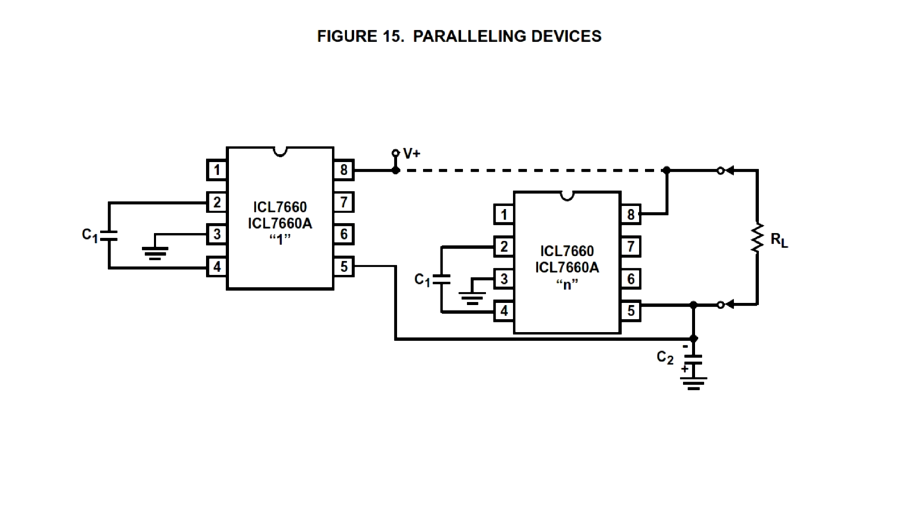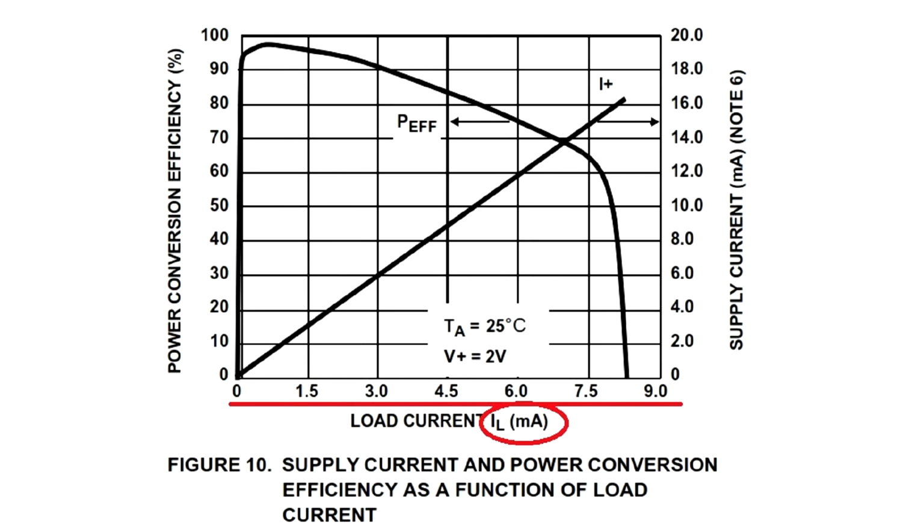But talking about the allowed range of currents, the biggest drawback of the charge pump becomes obvious. A single charge pump based on the ICL 7660 can only deliver a couple of milliamps. And even with several such devices in parallel, this topology could not be used to convert electrical power of more than even a few watts. Therefore, the charge pump is only used in very low power applications, and you most probably will not see a major power supply based on a charge pump topology.